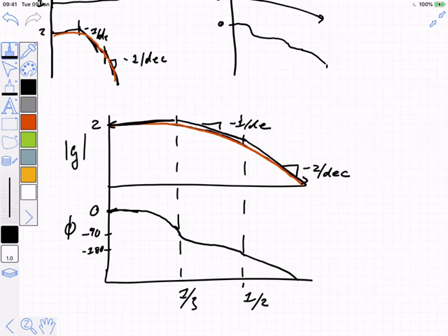And so you can look at this and say it's got to be a net second order system, because the asymptotic high frequency behavior goes down at -2. Right? So that tells me second order system. It looks like that phase is just going crazy, so it's probably got dead time, right? And so the first thing you do is you say, okay, I can look at this and infer that this is going to be of this shape.